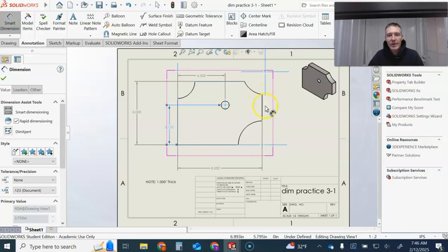So we have a choice. I prefer actually doing baseline. So from this side here, how far over? Or what we can do is measure from this edge over to the arc center. Either way, okay. This is a cool 8 inches. So if we measure over whatever it's 8 and whatever, then the math is really easy. Okay, so let's go ahead and do that.